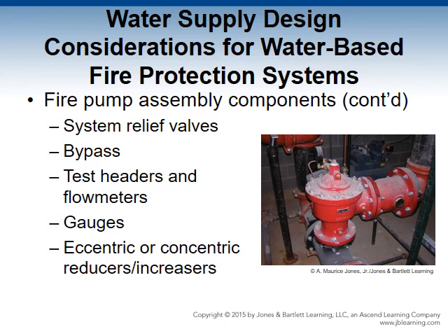Fire pump inspection, testing, maintenance, and service. First, you will have an acceptance test, which is made up of flushing the incoming suction side supply line before the pump connects to the suction piping, performing a 2-hour hydrostatic pressure test, a visual inspection of the fire pump assembly, and performing a field acceptance test. Periodic inspection, testing, maintenance, and service is composed of exercising the fire pump with electric drivers for 30 minutes a week with no water flow, and flow testing annually.